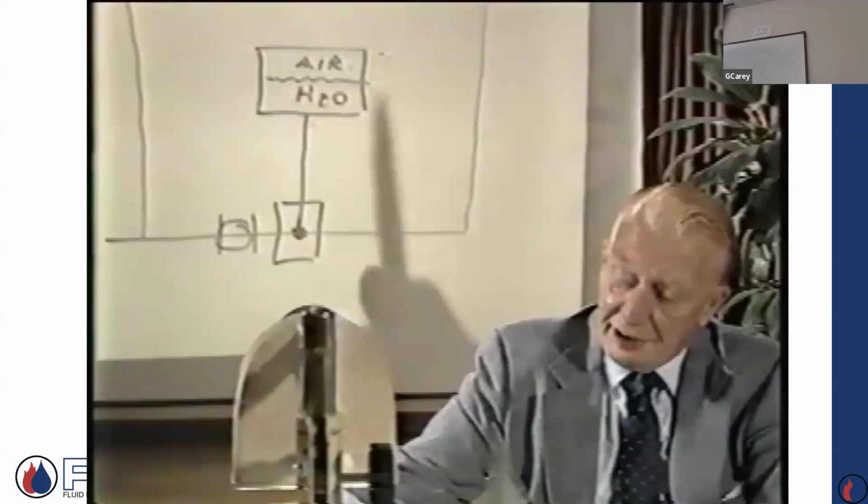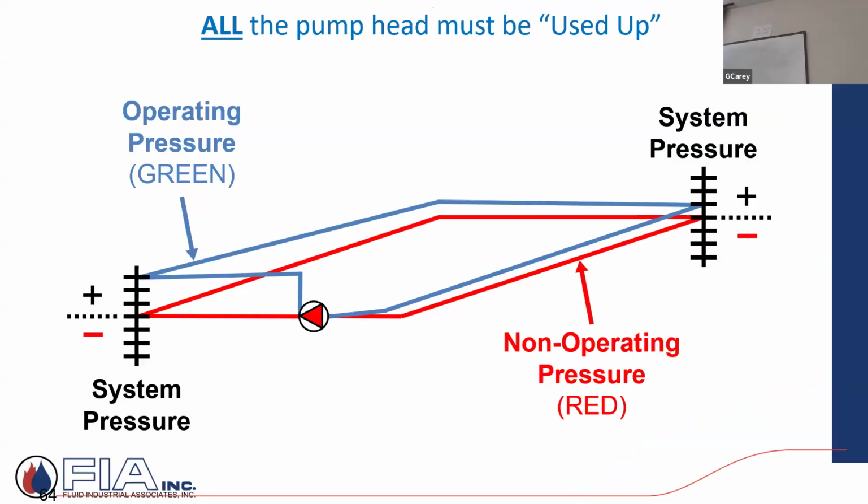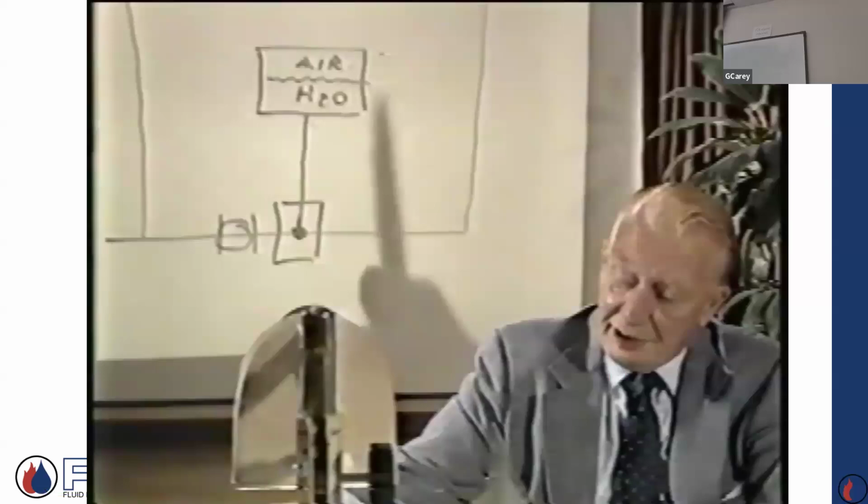But he talked about where the pump's located in the system relative to where the expansion tank ties into the system will determine when that pump turns on, is his pump pressure differential that I just talked about, is it additive to the system? Or sometimes if it's in the wrong location, that differential here will be negative. It'll drop, which is crazy, but it can really create operational problems. And so he actually wrote a paper and sent it to the engineering community through ASHRAE years ago about this proper pump location.